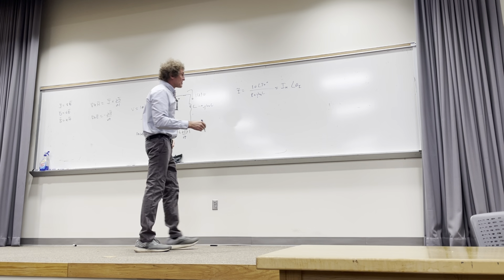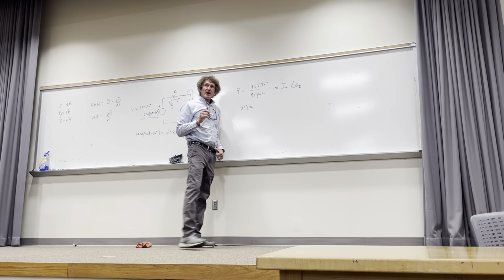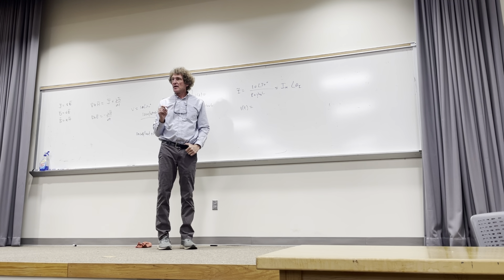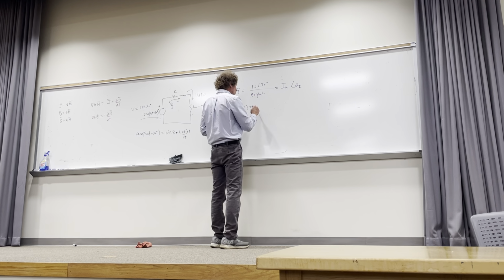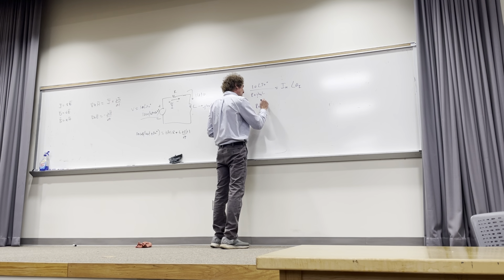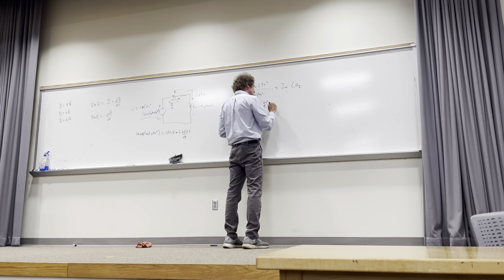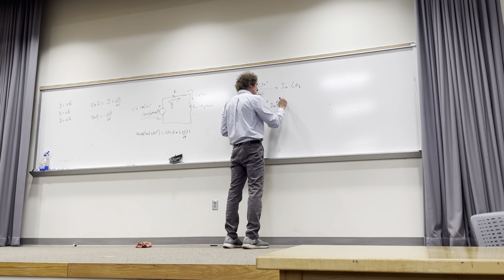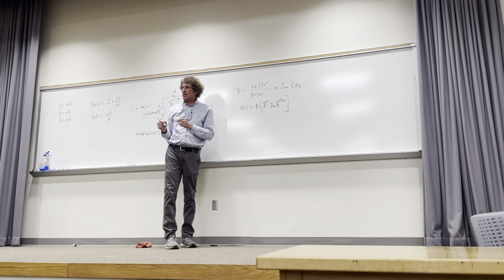Now, when I come over here, if I wanted to go to the time domain and get I of t, do y'all remember how to do that? It's something you don't even think about. You know it. Technically it's the real part of e to the j omega t times I phasor, right? I phasor would be Im e to the j angle theta I. Now I'm putting this from polar into exponential form. Y'all remember doing this, class?